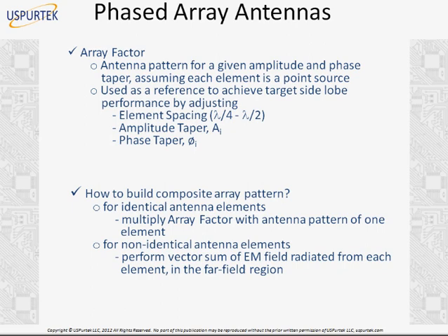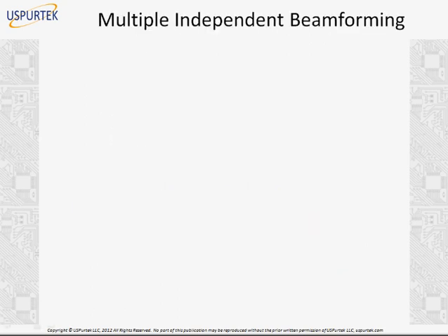of phased array antennas. Okay, for non-identical antenna elements, now it is much more challenging because you can't simply multiply the array factor with the antenna pattern. Here, you actually have to make measurements in the far field region and perform a vector sum of all the measurements created from each element. Okay.